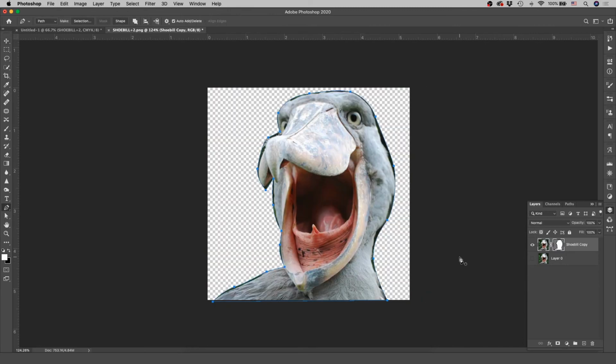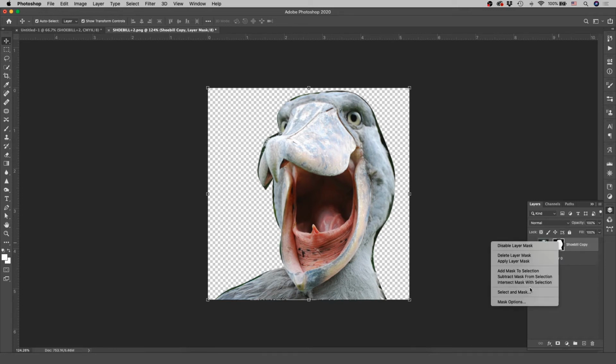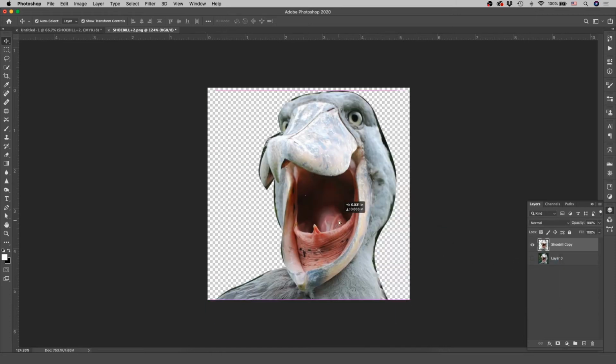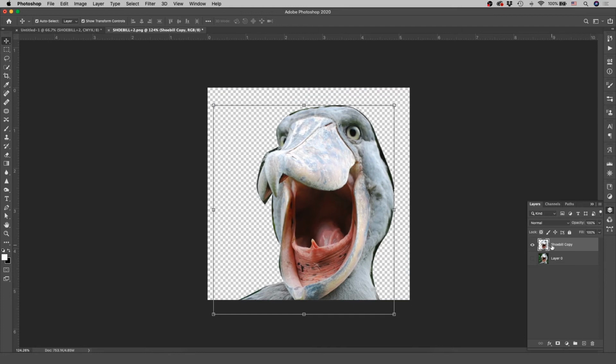So if you want the mask to actually cut the image, you can right click on the layer and hit rasterize vector mask. You can see that the background of the mask icon turns black. Then you can right click the mask again and hit apply layer mask. Now you can no longer adjust the points of the mask and have deleted the parts of the image the mask covered.